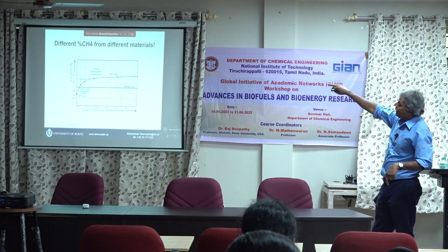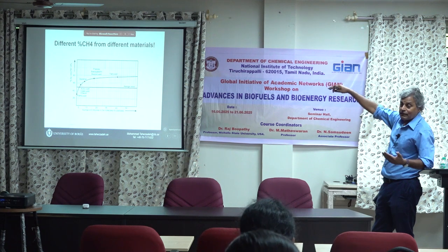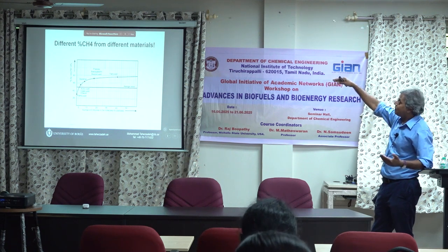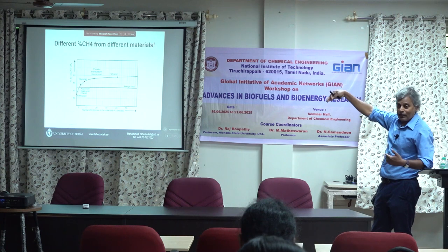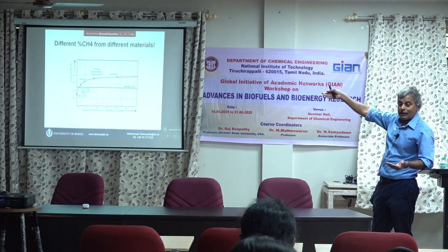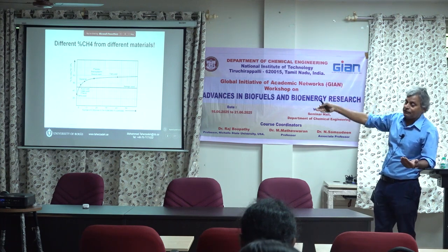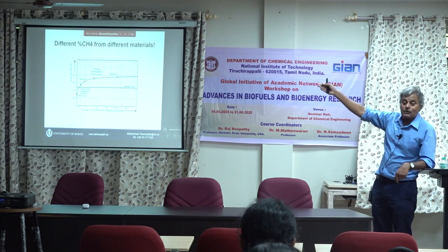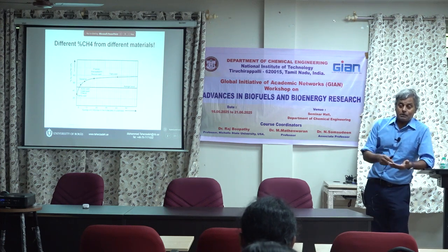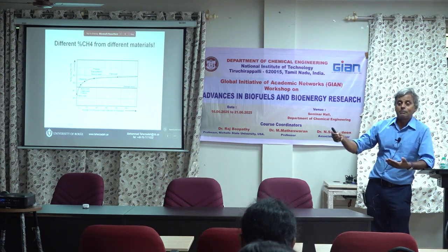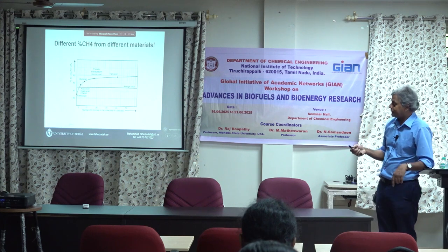If your substrate has benzene or benzoate aromatic compounds, you produce more methane gas. With long chain fatty acids, when digested, you get more methane gas. So the input, how much carbon is going in, makes a difference to how much methane is in your digester.